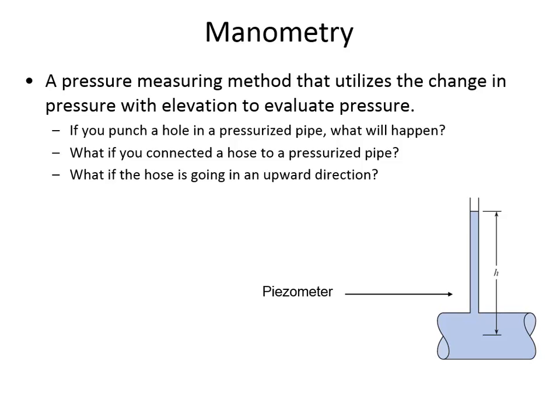But if the water isn't pressurized as much, minimum conditions might be 250 kilonewtons per meter squared. If it's that much, that's enough to keep contamination out of the pipe. Any lower than that, and there's a risk that there could be seepage into the pipe, or that when someone on a hill flushes the toilet, it could go the wrong way. During a low pressure event, that's the risk, that people who are at a really high point in the network are going to open their faucet, and that'll allow the water to flow into the network instead of out of the network and contaminate it.